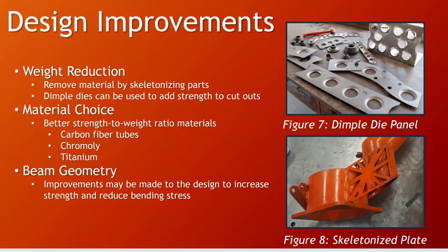The possibility of reducing weight is one of the most important concerns on a race car. Reducing weight in the rear suspension will decrease the power needed to drive the car, increase fuel efficiency, reduce the unsprung mass, and reduce the polar moment of inertia of the car.